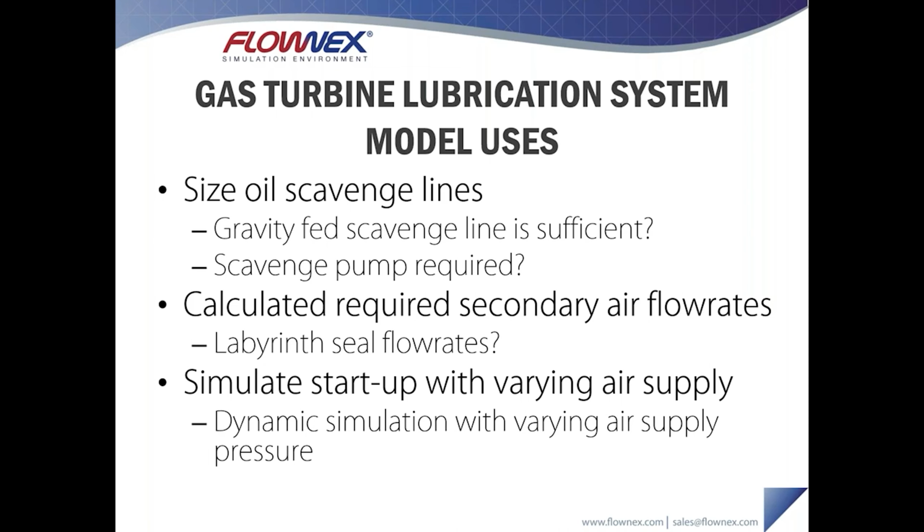So sizing that line is important, but then also above and beyond that, determining whether or not it's sufficient to have that line configured as a gravity-fed line, or whether you should be installing a scavenge pump, some kind of positive displacement pump like a gear pump, in that line to create that additional flow, if space is such an issue that the pipe diameter can't be large enough for a gravity-fed flow.